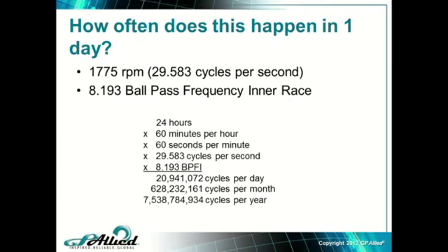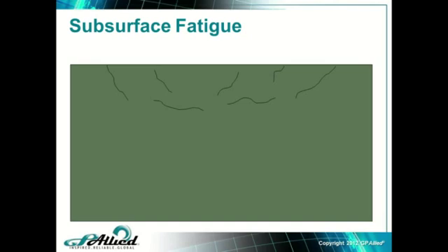So physically, what happens inside the bearing when we start to get this thing called fatigue? Well, it works exactly like this. It looks exactly like this. We call this subsurface fatigue. So you can imagine roller after roller after roller coming by and compressing that spot, and then it relieves, and this happens a couple of billion times a year. It's 7.6 billion if it ran 24/7 all year long. And after a while, the surface of the race literally starts to exhibit what's called rolling contact fatigue. Now we'll leave all the fancy stuff for the AST people, but we'll just call it subsurface fatigue.